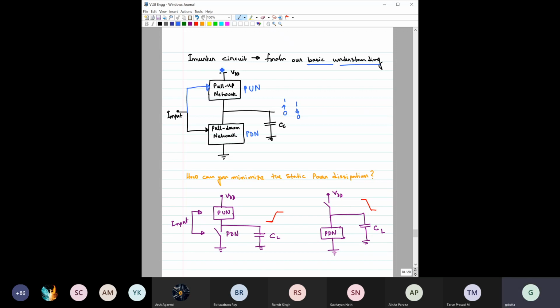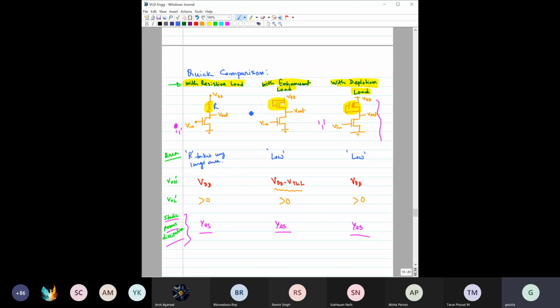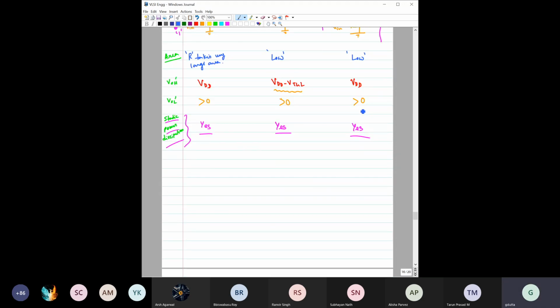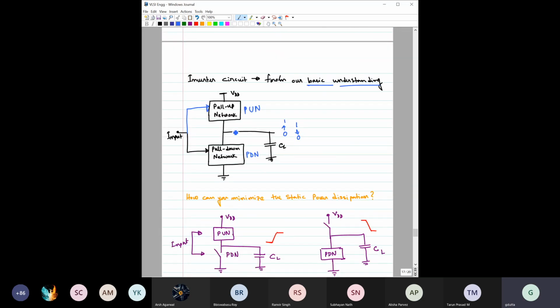No harm in this, right? We can connect this input to both the pull up network and the pull down network. So far we do not need to, because if you see the earlier techniques, here is the resistor, so there is no need of any input. Here the gate input is already shorted with here. Here this input is already connected with here. So we do not have any requirement of connecting this input to the load or the pull up network. But if there is any requirement from any design point of view, then we are free to do that.